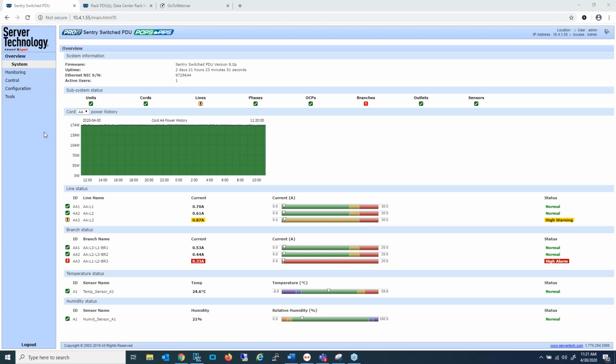Well, yes. I mean, you would have to do it manually. There's no magic button that will just read the values and then adjust on the fly. You would have to look at those values first and then go set those thresholds appropriately. The Pro Series PDUs have the ability to have up to 4 PDUs exist through a single unified interface. Most commonly is one master PDU and one link PDU, so 2 PDUs per cabinet.